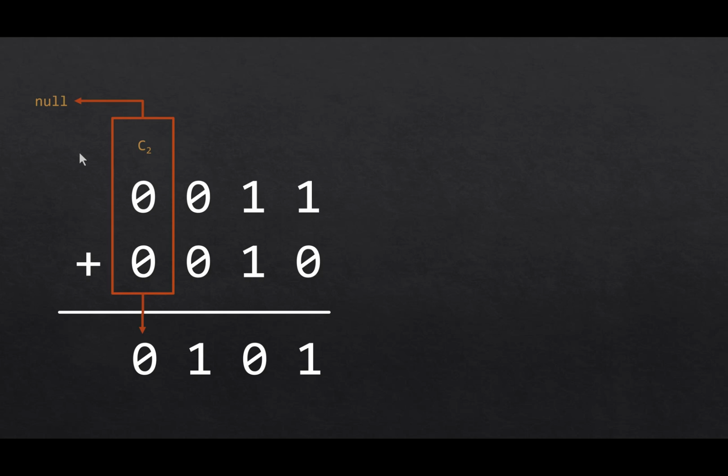So this kind of shows how, using a combination of half adders and full adders, components that are just built up out of logic gates, a computer can add two numbers. And all it's doing is performing very simple primitive operations on bits. It doesn't understand what those bits mean. It doesn't understand what numbers mean. But it works out that if you wire this all up correctly, the pattern of bits of the output actually represents the sum of the two numbers that were the two inputs. So that is how computers do addition.